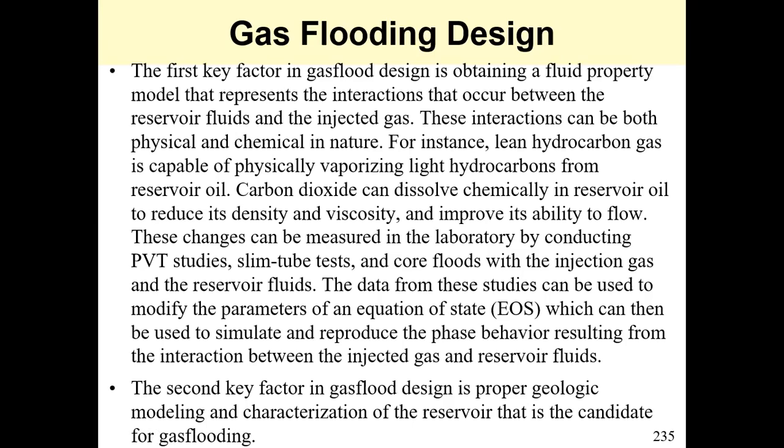I know that we ought to be discussing immiscible gas flooding, but it's difficult to talk about gas flooding without referring to some degree of miscibility. So a key thing is to fit an equation of state to your recovery process as modeled using PVT studies or slim tube tests or core flood experiments.